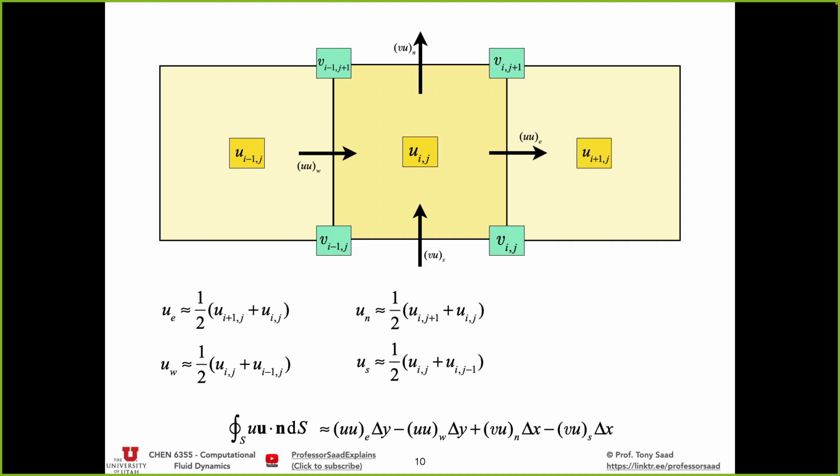It gets really complicated. But if you do it once like this on the board, you're honest. You don't have to do it again. You can take this blindly and implement it and be just fine. So indeed, v north is the average of those two velocities on the upper corners, upper left and upper right. And what about the last one, v south? Here, v south is going to be the average of these two. These are second order approximations.